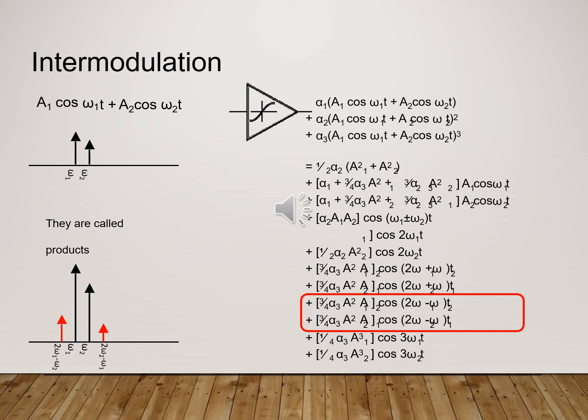and we would need ideal filters to split them. So, nonlinear distortion results from systems where the output signal is not exactly proportional to the input signal, and harmonics or intermodulation products are generated. This impairment is introduced by the nonlinear behavior in the transceiver and needs to be considered.